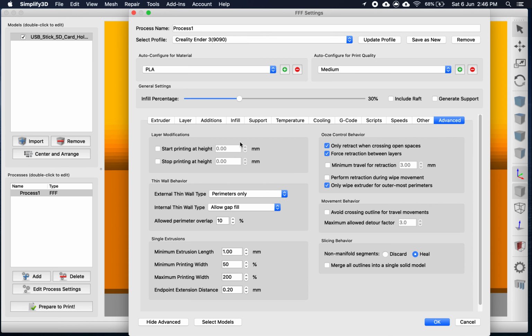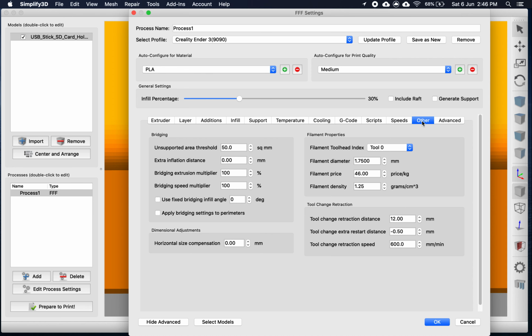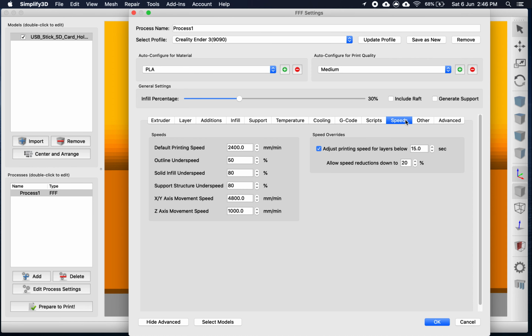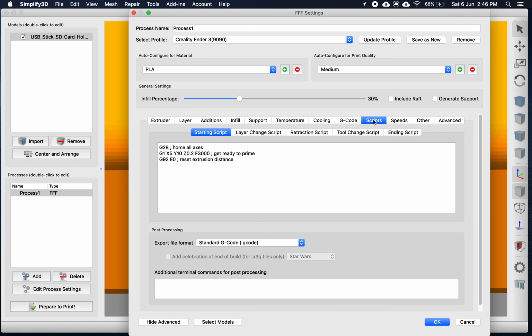On this side, don't change anything. They have others also. Don't change if you don't know what you're doing. Speed, no, don't change. We are almost at the top speed already, but if you go more than that, then you will have a distortion, the nozzle moves too fast, all this kind of stuff. Don't change anything if you don't know what you're doing, because it might harm the machine. The machine will crash. We really tested all those code.